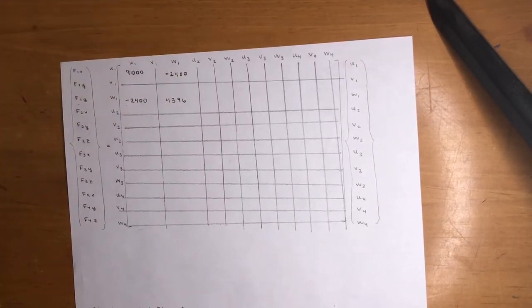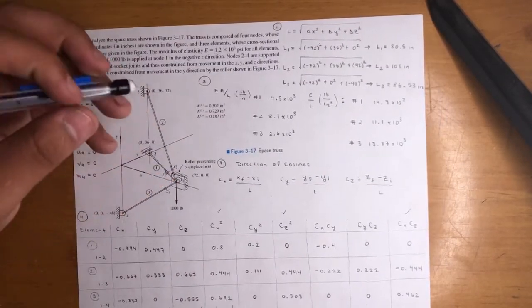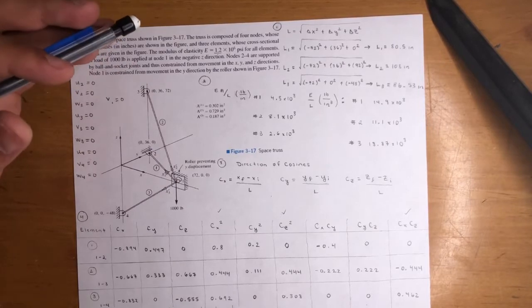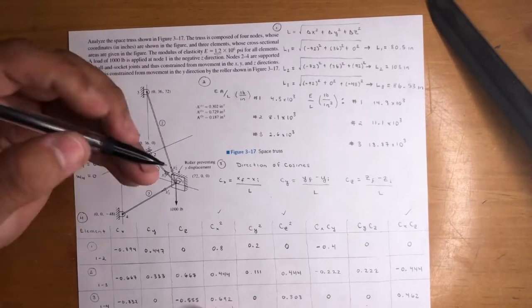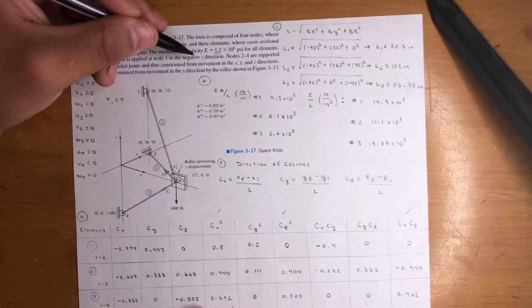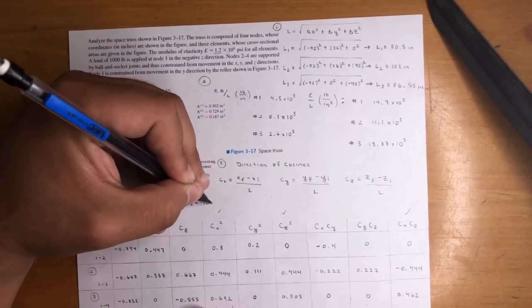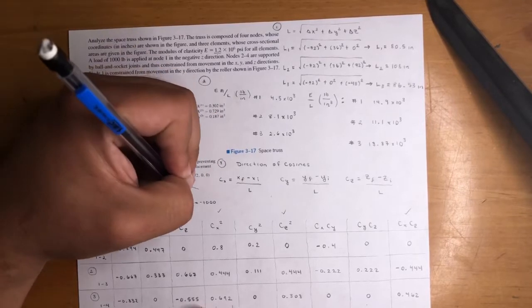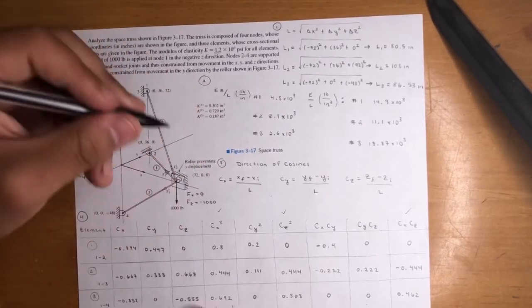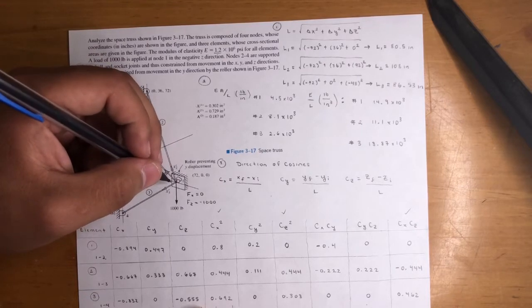And that means we could go ahead and start pretty much solving the equations, right? We have 2 more boundary conditions. Hold on. Now look, it says roller preventing Y displacement. That means if it's preventing displacement, there's a force acting on it. It tells you here, right? 1,000 pounds, node 1, negative Z. So that means F of Z is negative 1,000. And just by looking at the schematic, force of X is 0. And normally it would have been Y of 0, but they told us it's preventing displacement. So that means there's a reaction force at Y.